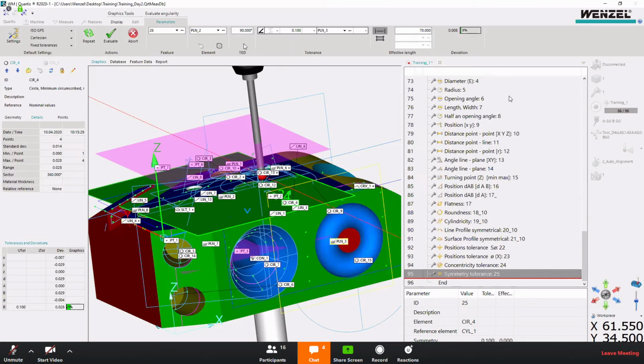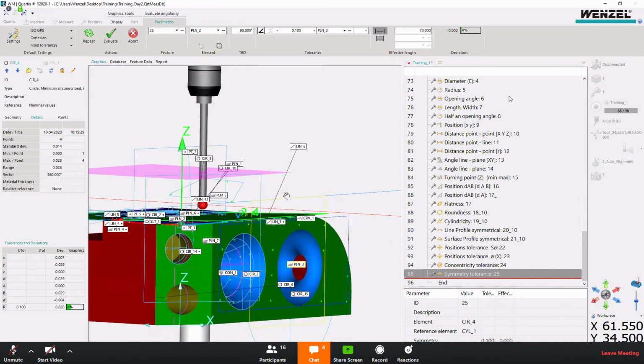Okay, and then you will see these theoretical exact dimensions, which are a bit similar to what we had in true position just now. So in the drawings, if they ask you to evaluate the angularity, it will also give you a value in the box, and state the theoretical exact angle between this top plane and the side plane, which is 90.